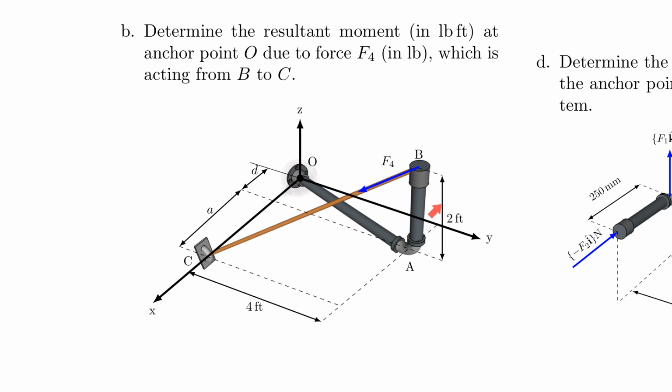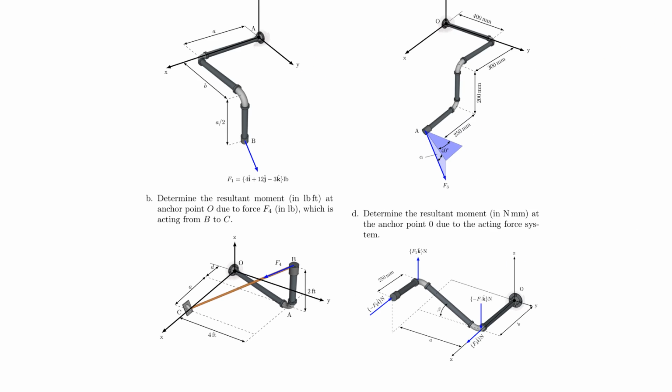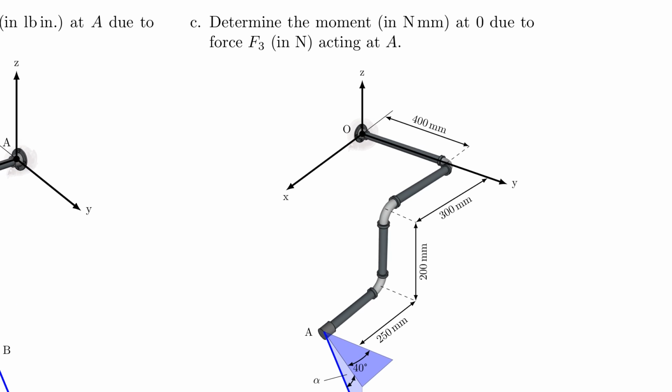So you have a height of 2 feet here, 4 feet, and then this is A and this is D, and that really can help you to form, if you want to use a unit vector, the unit vector here, and that forms then the force along this cable. So you can really describe this force using either unit vector or similar triangle. It's up to you, but the bottom line is you use that ijk component of that force and cross that with the lever arm.